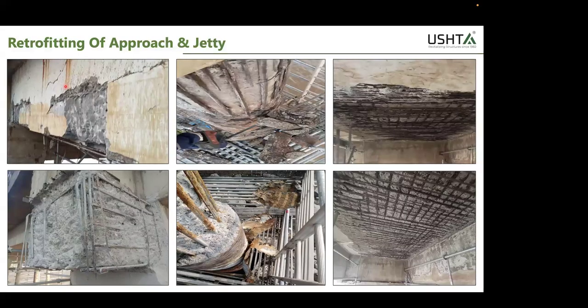So all these properties, if they're not matched, would lead to shear bond failure, which is a very classic example here. And in this portion also, new reinforcement was added, but that corroded very fast because of the difference in polarity, and because they didn't treat the corrosion. And secondly, they were not able to extract chloride, which was already present in the concrete. So that also diffused from inside to the new concrete, and because of diffusion, you could see a lot of corrosion in the concrete. And here you see the repaired slab has also given way. Similarly for the pile caps also.